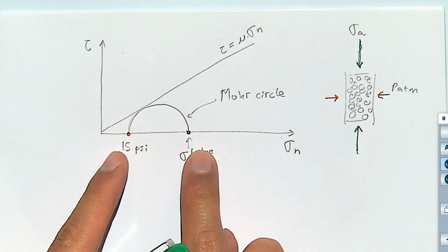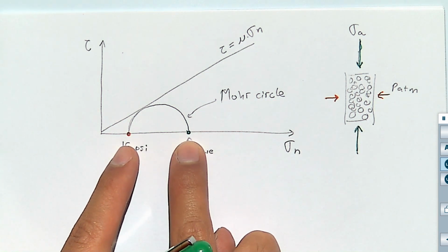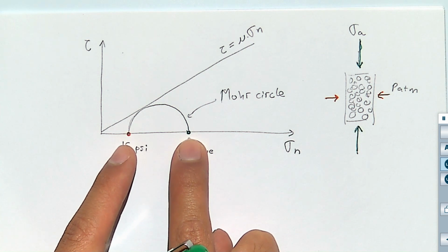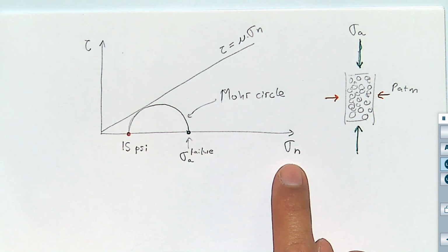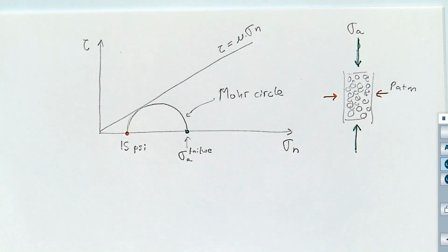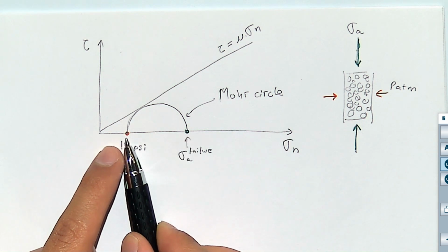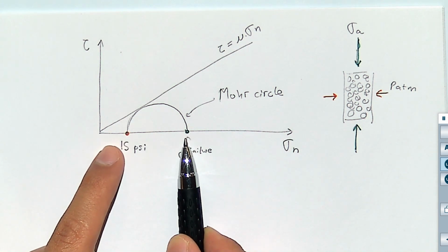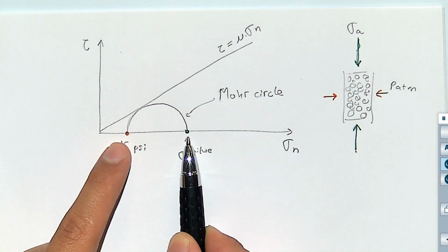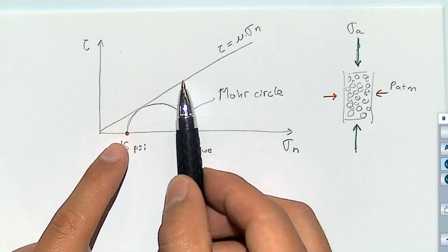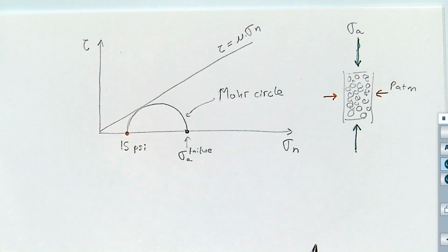And in this type of plot, they will plot as 2 points on the x-axis, which is the axis of normal stresses. All right. So for principal stresses, normal stress is different than 0 and shear stress is equal to 0. So let's see now what this circle is and how it links to that line.